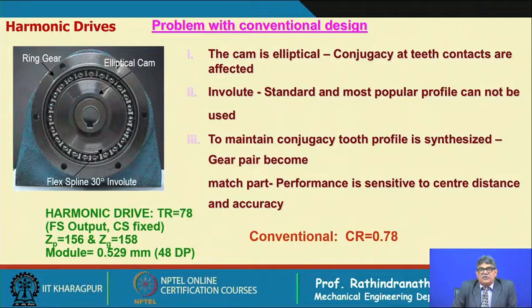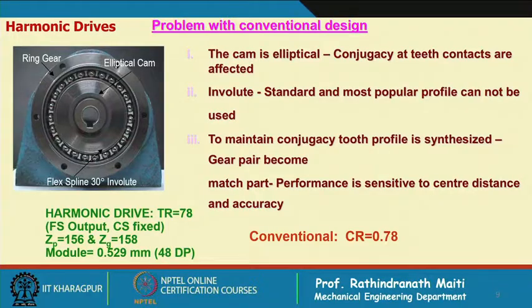So, if the contact ratio is 0.78, then definitely the gearing action is not available. We have the idea that the contact ratio should be at least 1, and in practice it should be more than 1, so that there is no failure, but 0.78 definitely would not work. So, with the 30° involute teeth, there is definitely multiple contact, a contact beyond the normal contact at the tip.